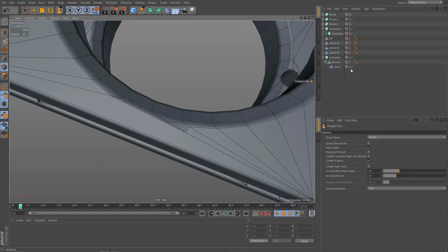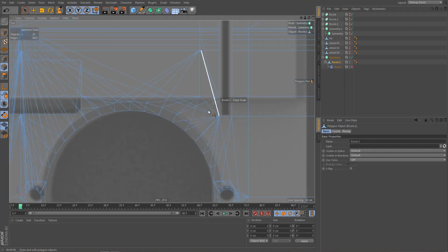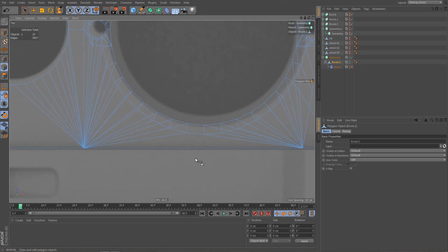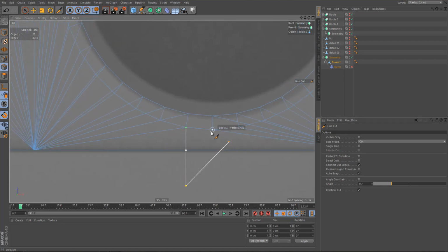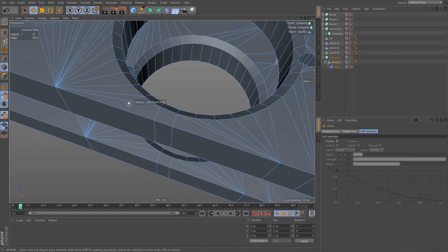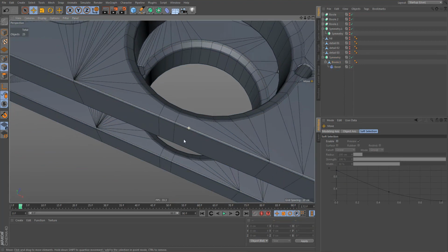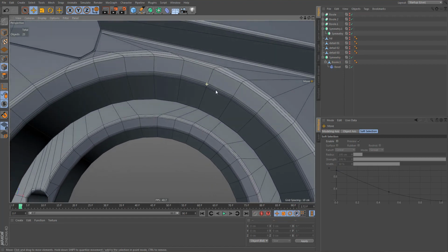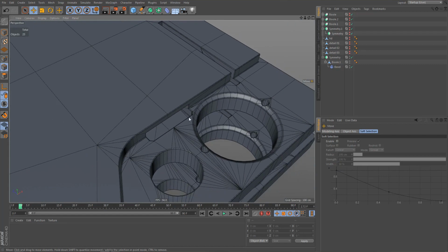And we're not getting very nice bevels over here either. So I'll make another cut, switch off visible only, and I'm going to make 2 cuts actually. Like so. Let's remove these edges. And let's see how that bevel looks now. You can see that's looking a lot cleaner. Now we do get a similar issue back here as well, but it's not that bad, so I'm not going to change anything over here.